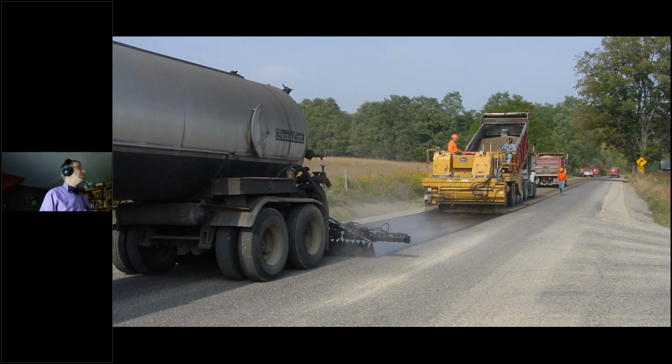Somebody noticed in here, it may stay brown for a while if placed in cooler weather for microsurfacing or chip seal. Yeah, the factors that affect how long it takes to break are whether it's a rapid set, a medium set, or a slow set. We're not going to use slow set on a chip seal, obviously. The weather makes a difference. Humidity can make quite a bit of difference. Wind can make a difference because it helps cause evaporation on the surface, whether you're in the shade or not in the shade.